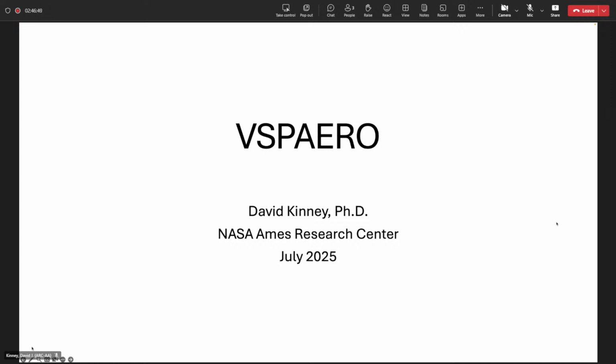So when you start to put a wake on the back of a fuselage in some way, then yes, it will start to pick up a load. It'll carry a force, not just a moment. But without a wake off of a body, basically the only place you're going to get forces is where there's a wake, and otherwise things just contribute to moment.